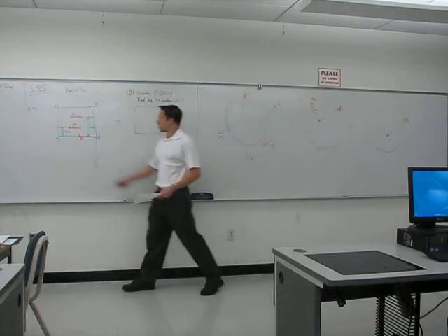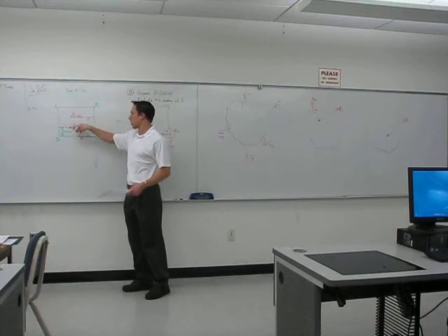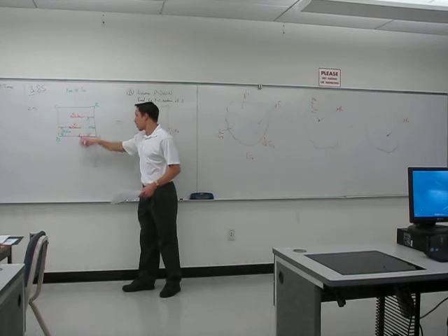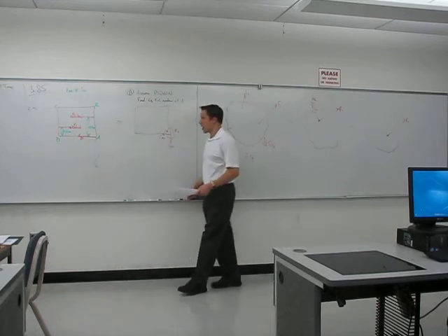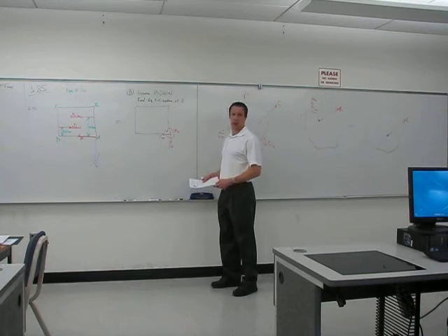So what I'm going to do is take all of these forces. One is already acting at the point A, so I really just have to worry about F1 and F2. I'm going to move them to the point A, add up all three forces, and when I move those F1 and F2 forces, I had to put moment vectors in. Well, when I add those all up, I'll get my moment vector for A.